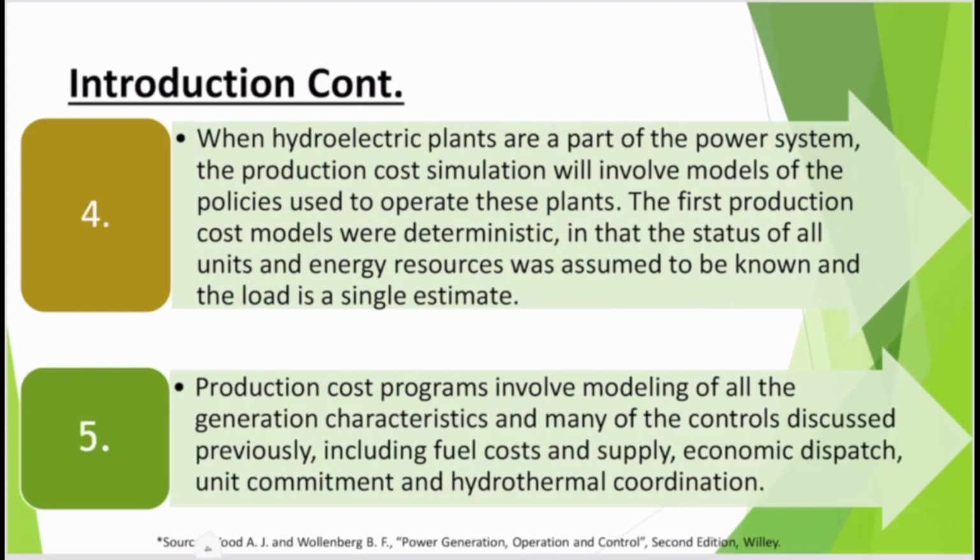The first production cost models were deterministic, in that the status of all units and energy resources was assumed to be known and the load is a single estimate. But practically, assuming a load which is fixed is not true, because let's say I'm assuming the load is 100 megawatt tomorrow at 5 p.m., which is not necessarily true.